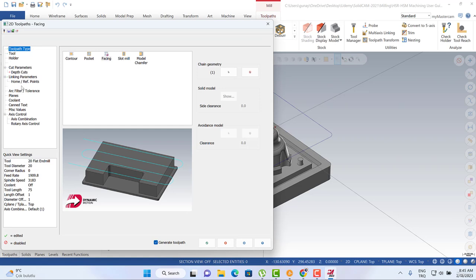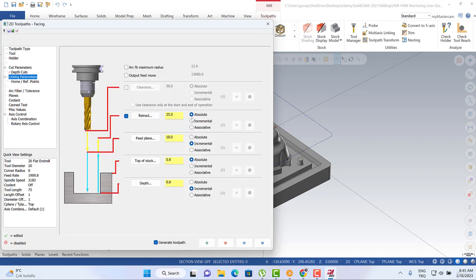But when we turn to the linking parameters, if you select the absolute coordinate system, it means that I don't care about where my profile is. Okay? X and Y axis are of course quite important, but when we consider the z-axis, it is not important.